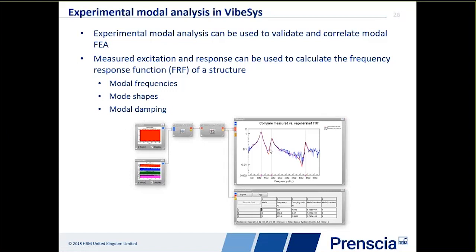And if we were to visualize, for example, a simple mode shape, you might first envision something like a guitar string. And as that guitar string is struck, one of the first mode shapes would be essentially an up-down gentle heaving. A higher order mode shape might be a sine wave where you see a single sine wave. And as you continue to go higher in the mode shapes, you're going to see more and more sine waves. And many times those are going to be smaller in amplitude as well. And the only way in which we can experimentally describe those mode shapes is if we had measured it in several locations along the guitar string or along the structure in which you're trying to characterize.